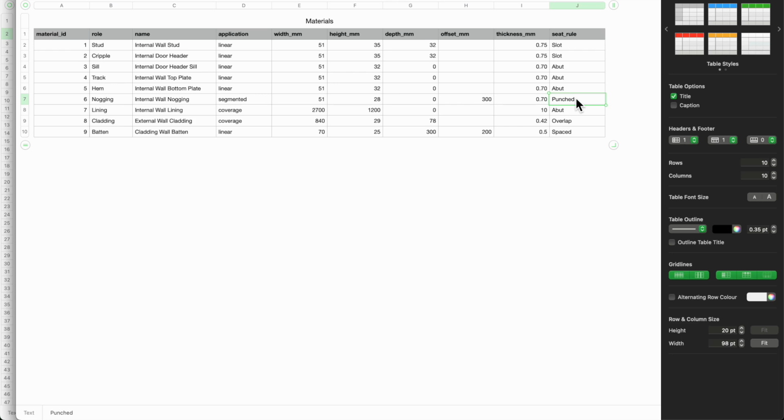And the reason we're defining this is because if we say we need 7 lengths but one's got to be cut, we don't want any of those cuts to be in between punched holes. We want them to be right on a punched hole, so then it falls on a stud.